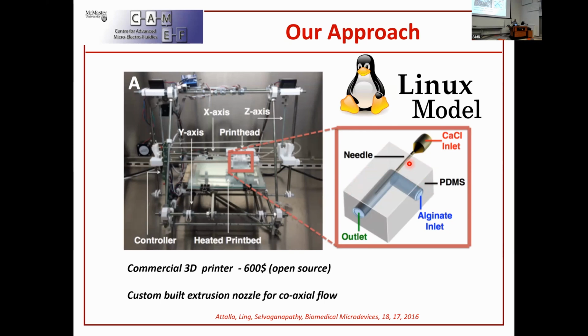And what we started out was to flow a cross-linking agent at the center, and a cross-linkable polymer on the outside. And so our example was calcium alginate. So you flow alginate on the outside, calcium on the inside, right? And when you do that, the calcium immediately starts cross-linking your alginate inside out, right? And that was sort of the difference there. And so your walls inside become stronger. And as the calcium diffuses out, you get more and more of the cross-linking. But the polymer outside is still a polymer, ungelled polymer, and it is capable of flow.